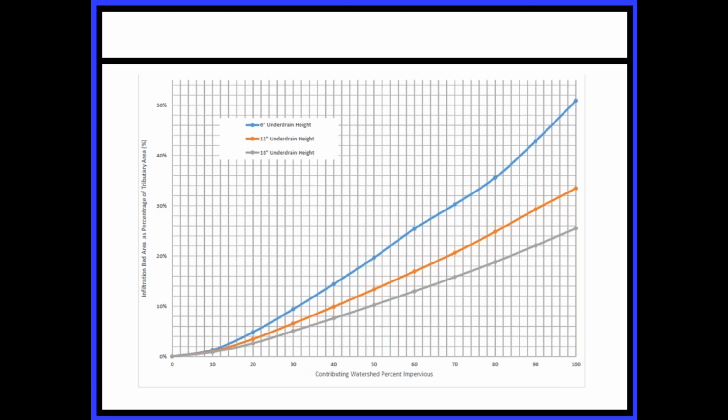What we found is that at about 18 inches of water column depth for infiltration, the value of Darcy's law decreases. So basically, the more head that is created, the less value that head has for infiltration. Generally what we're finding is that about 18 inches of water is a good depth for infiltration.